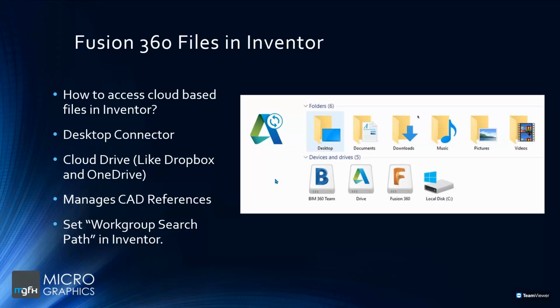If I upload the assembly file only, the IAM file, to that drive, it will prompt to ask for a project, basically an Inventor project. What Inventor project is that assembly stored under? And it uses that project and the assembly to find all of the related files.